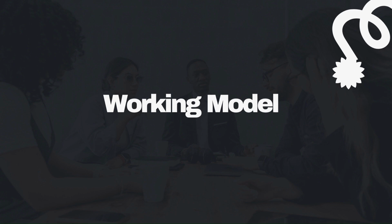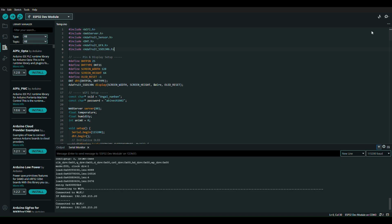So let's get into the working model. So let's get into the libraries. First of all, we have WiFi.h, which helps to connect the ESP32 via Wi-Fi. Then WebServer helps the ESP32 create a small web server via HTTP. Then Adafruit sensor and DHT11 for using the DHT11 temperature and humidity sensor. Then Adafruit GFX.h, then Adafruit SSD1306.h used to control the OLED screen with graphics and text.